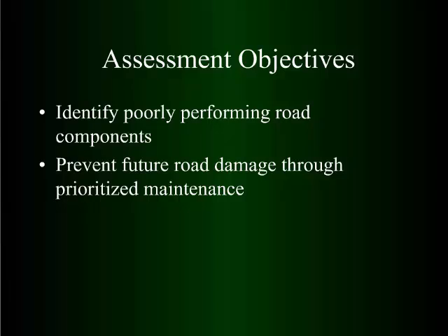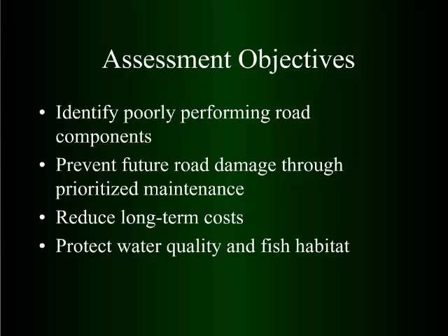Many of your drainage problems, you need to start kind of at the top and work your way down to fix the problems. Sometimes you just send the problem further downhill. So you kind of need to look at the whole situation, decide where you need to start. The benefit of identifying the problems and then fixing them can be reduced long-term costs, especially if you have some roads that you're doing some surface rocking. If you can keep from losing that off due to erosion, you can save a lot of money. The other is just your normal maintenance of grading your roads and keeping them smooth. The other benefit of fixing your problems is protecting the water quality and fish habitat.